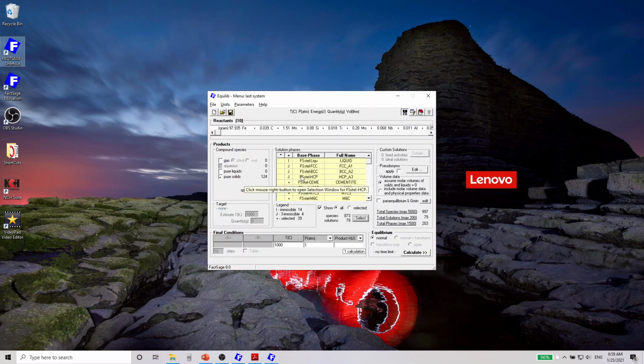And then for all the carbide phases, these are the carbide phases, we'll put I option, which is two-phase immiscibility. So after putting all the FCC, BCC and HCP phases as with J option, which is three-phase immiscibility, we add all the carbide phases to be two-phase immiscibility.